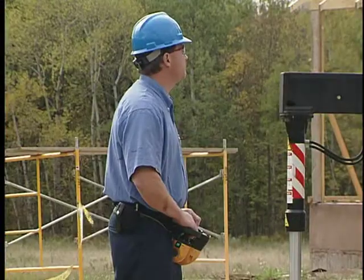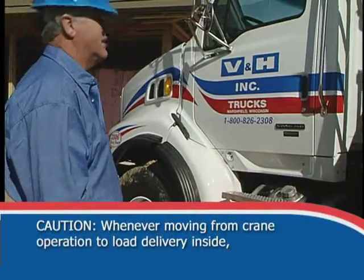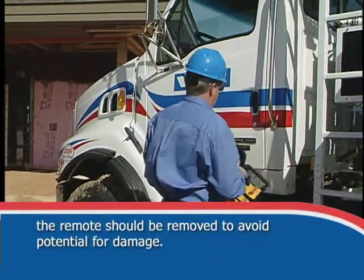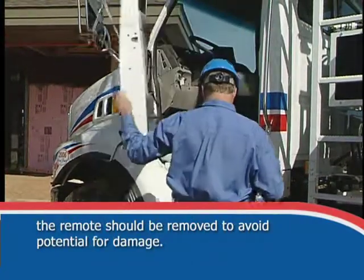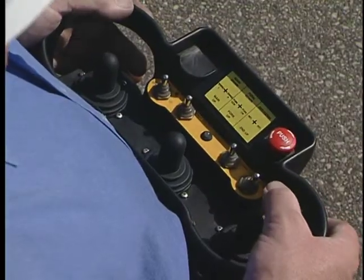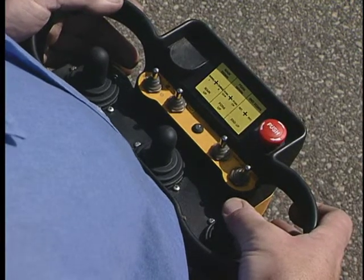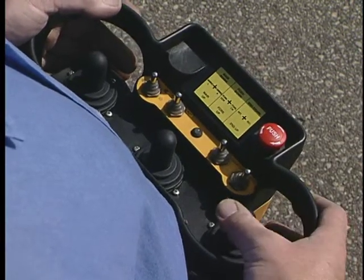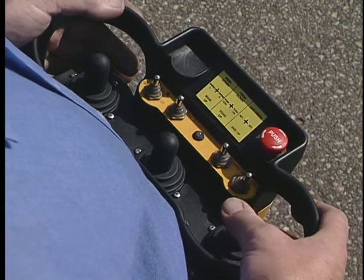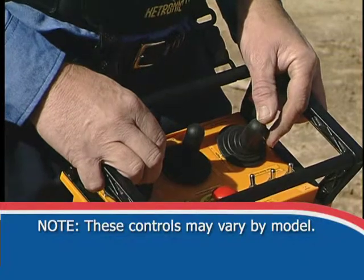The remote is strapped to the body to eliminate fatigue. Whenever moving from crane operations to load delivery inside, the remote should be removed to avoid potential for damage. The remote control differs from most platform controls because it has 2 or more joysticks which control all the operations done by the platform group of joystick pedal controls. Radio remote controls may vary by crane model.